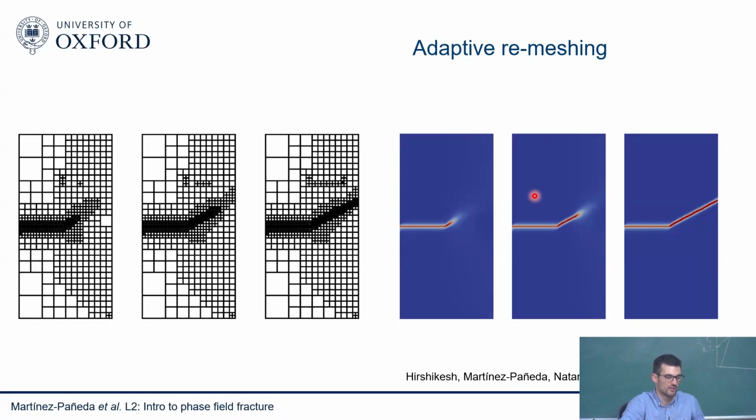That's what I'm saying. So normally, when I mesh, I just use a uniform mesh all over the place if I don't know where the crack is going to go. So what I would do, if I'm not using adaptive remeshing, is use maybe a mesh like this one, that I know is probably too coarse, but I'll put this mesh everywhere. Then I'll see that the crack is deflecting in that direction. So then I will use a finer mesh like this one over this square. In the second calculation, that will be the end of it. But you can also use these kinds of techniques where you start with a mesh like this, and then depending on the phase field, you start making your elements smaller, smaller, smaller, and then eventually you get the right result.